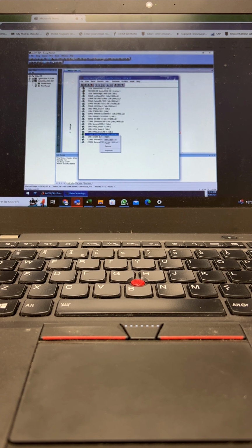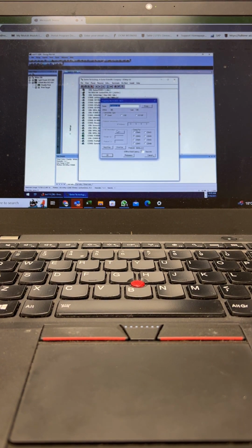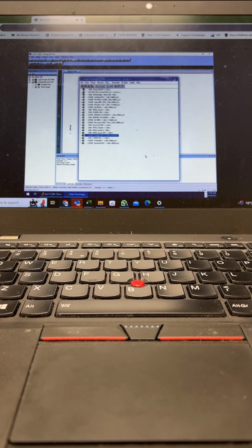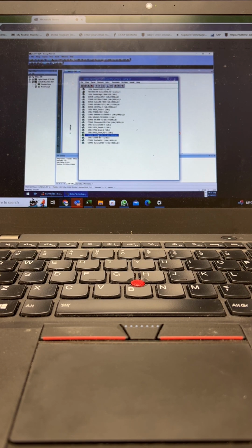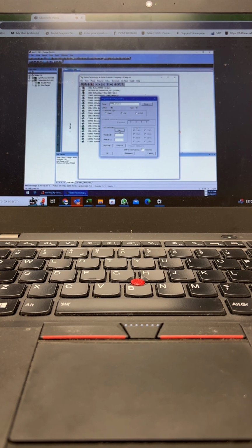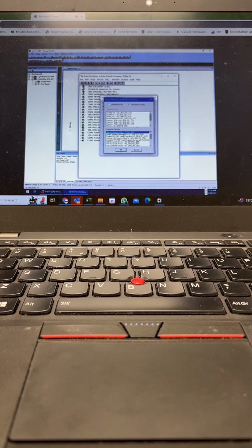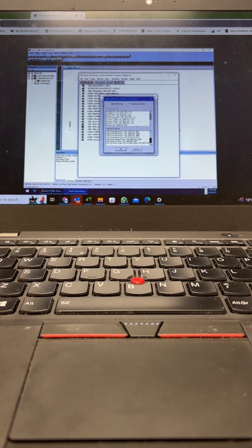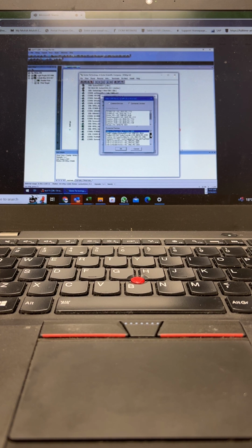For the GraphTech plotters, let's see, there's one of the recipes. You do have the USB information, so typically the first time you output, it'll ask you to select the connected device. So you'll need to select the correct USB VID and PID information for that device. Right now I don't have it installed, but you would have to select the GraphTech that was actually on there, or whatever those settings were.